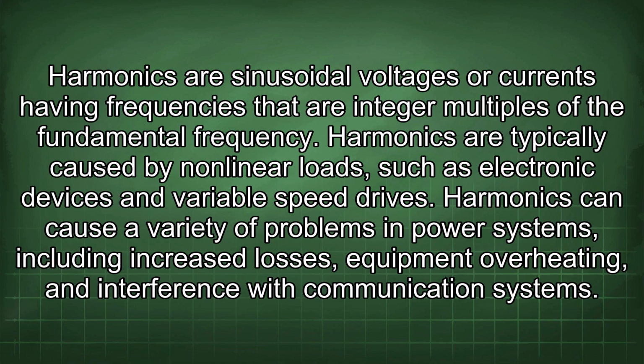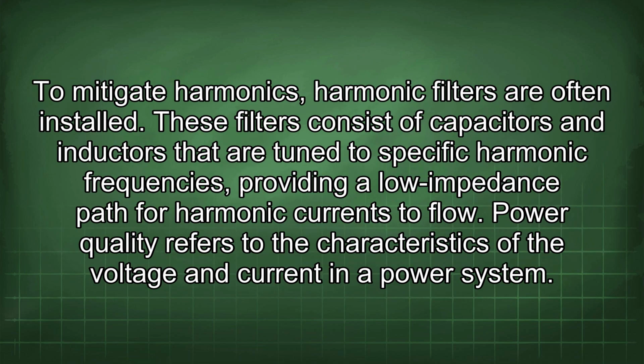Harmonics are sinusoidal voltages or currents having frequencies that are integer multiples of the fundamental frequency. Harmonics are typically caused by nonlinear loads, such as electronic devices and variable speed drives. Harmonics can cause a variety of problems in power systems, including increased losses, equipment overheating, and interference with communication systems. To mitigate harmonics, harmonic filters are often installed.